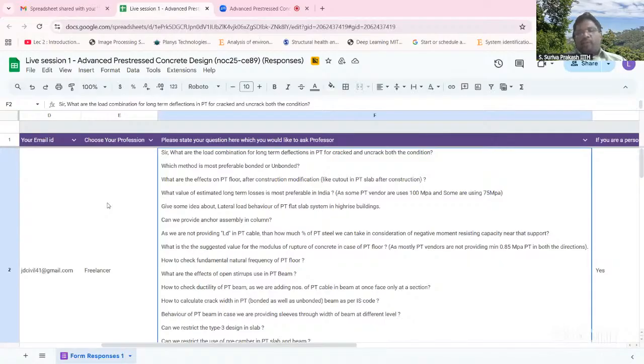No, 100%. See, LD, development length in PT cable, because you have anchorages, right? So anchorages are holding all these things. Typically, the rebar will be able to develop the force very quickly, because it's like headed bars, right? Headed bars have very less development length. Something similar to that. Now you have an anchor block that is holding all the bars, so quickly it will be able to develop the stress you want. So that is typically not a concern in a PT system.